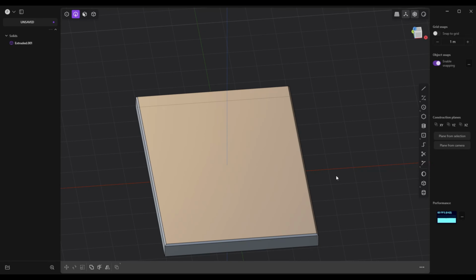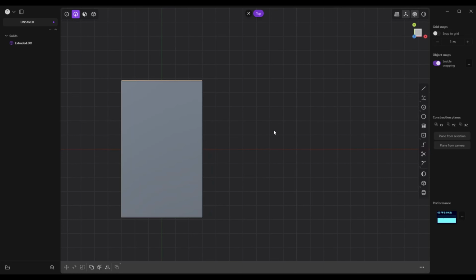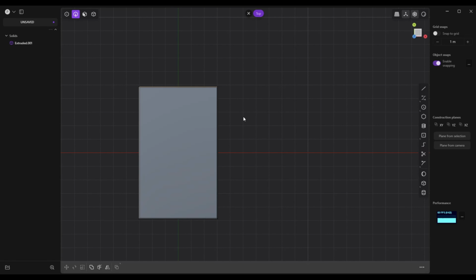And what we can do next is create that outer shape that's going around the play button. So we're going to jump to our top view and let's do it on the side and then move it in, okay? So we're going to grab this guy, control point curve, all right? And if you don't see that, left click and hold, and then there it is.